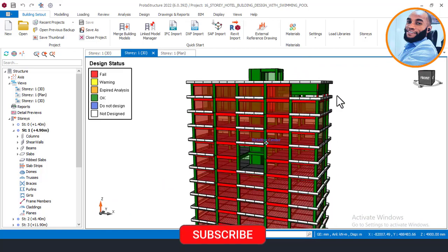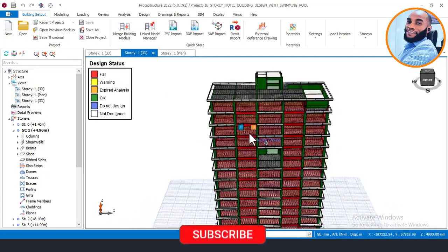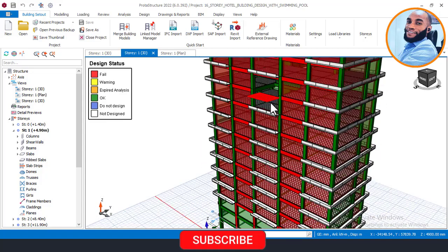Although most of our members are still showing okay, as you can see, green means okay and red means failure. So those members that are showing green are okay and the sizes are okay, and those members that are showing red mean that the sizes are not sufficient to carry the weight.